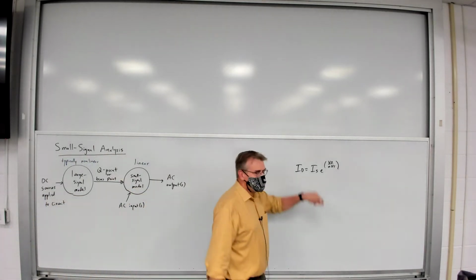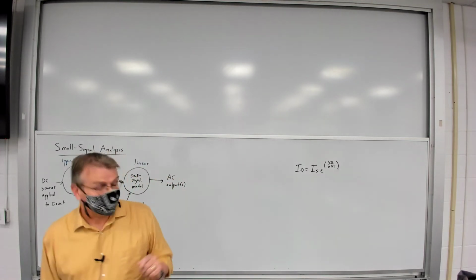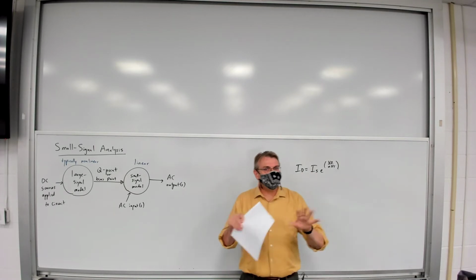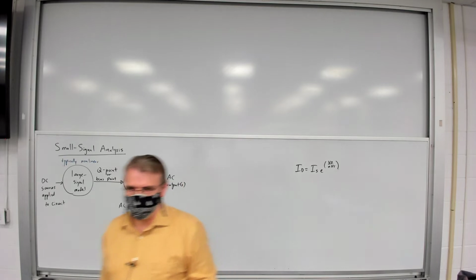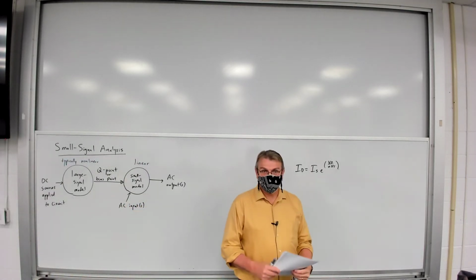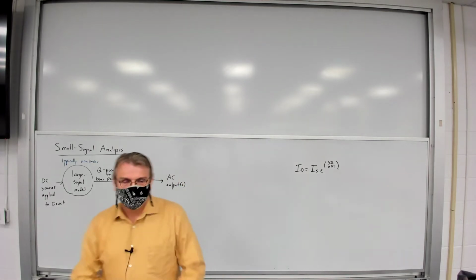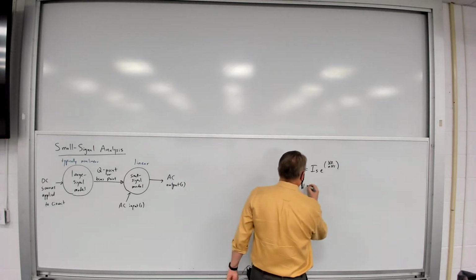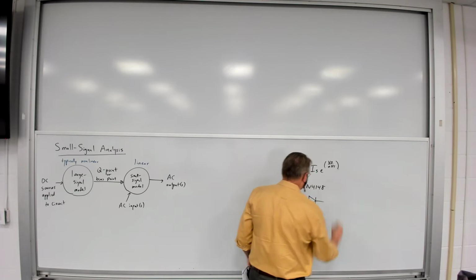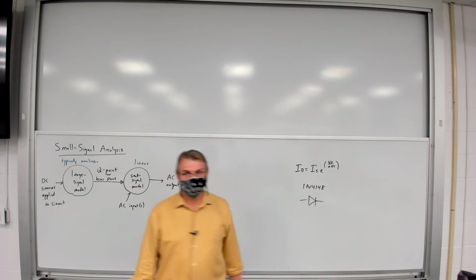This equation, the ideal diode equation, or I should say the p-n diode equation, is a first-order theoretical equation. What you're going to find is when you simulate a diode in LTspice, unless you use the basic diode model, so for example a 1N4148 diode, an actual silicon diode, the model they use is much more complex than just what that simple little equation does.